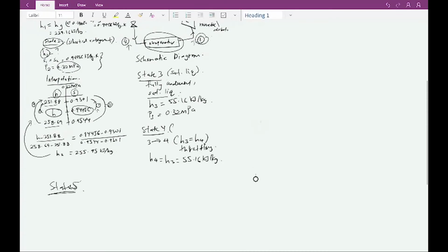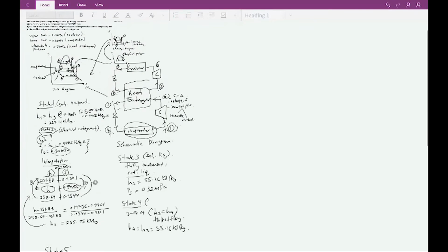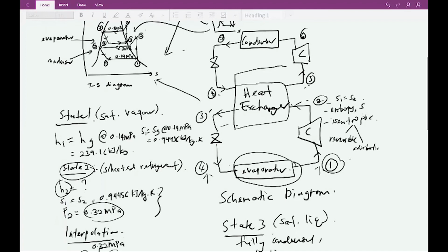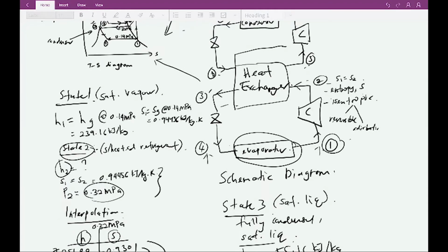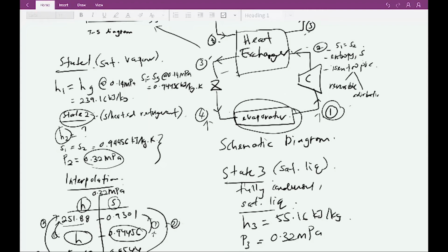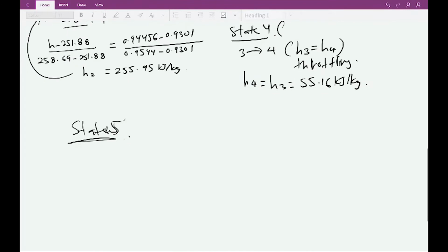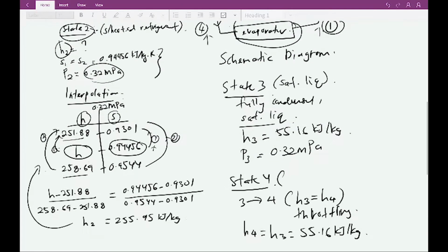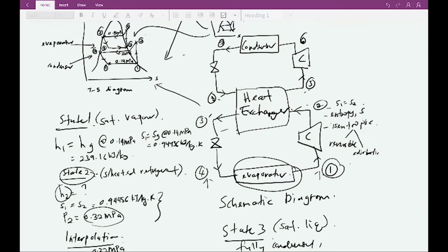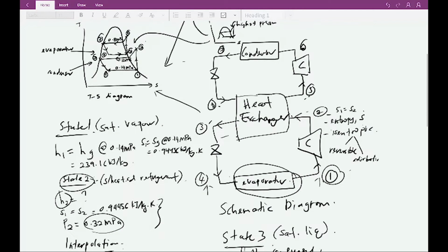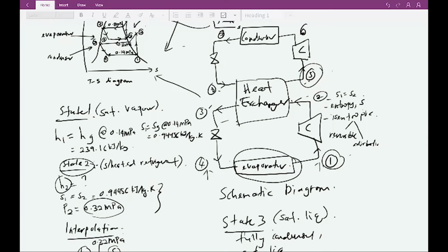Okay, state 5 here is quite similar between the upper cycle and the lower cycle, because it is still an ideal vapor compression cycle, which is copied. We copy it together and then put it on your upper side. So state 5 is basically quite similar to state 1 from the lower cycle, because here state 5 exits the evaporator inside the heat exchanger.